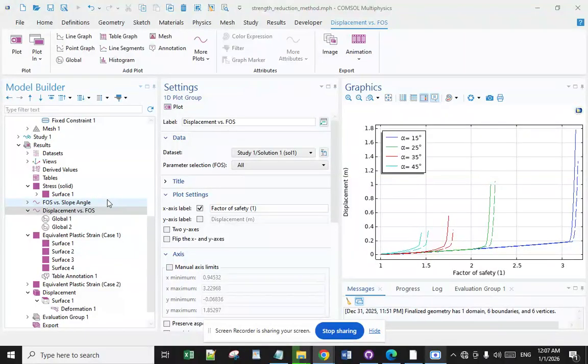One usage of margin of safety is as a measure of capability like FOS. The other usage of MS is as a measure of satisfying design requirements, which means requirement verification. Margin of safety can be conceptualized along with the reserve factor explained below to represent how much of the structure's total capability is held in reserve during loading.